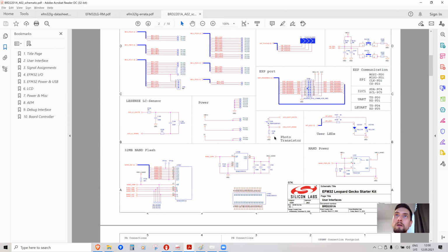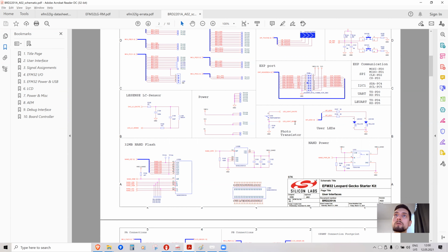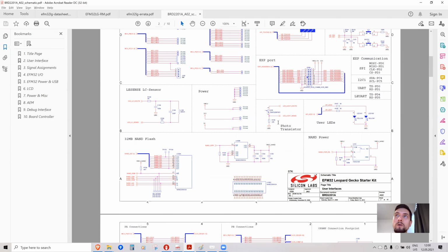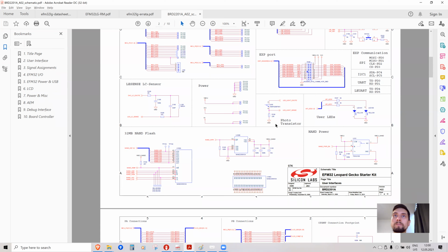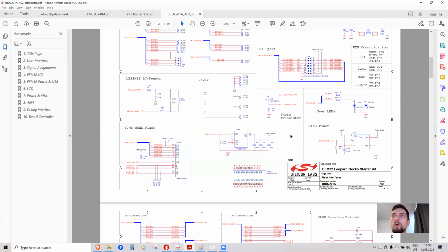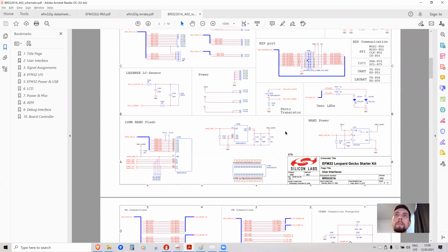But as we can see here, there's no capacitor, so there's no analog filtering on the board, which is not great because if there is some high frequency noise because of the anti-aliasing or aliasing thing, it can go into our schematic and get us wrong results. So analog filtering on the board is practically always, almost a mandatory thing.